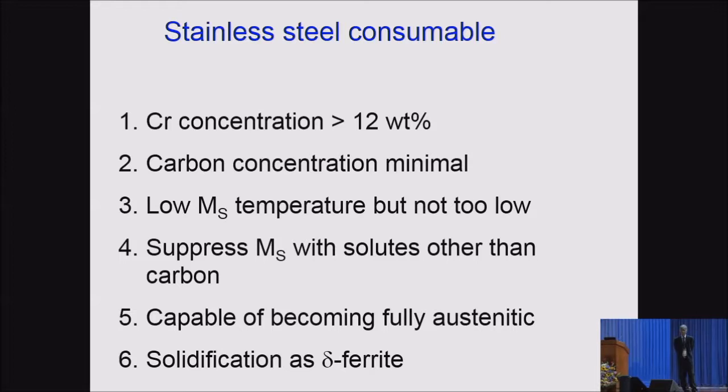The first is, obviously, for it to be stainless, you need a chromium concentration which is greater than about 12%, so that you get a chromium oxide film on the surface which protects the substrate. And it's a chromium oxide film which regenerates itself. So if you scratch the material, it will form instantly again.